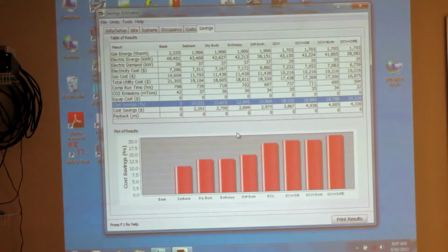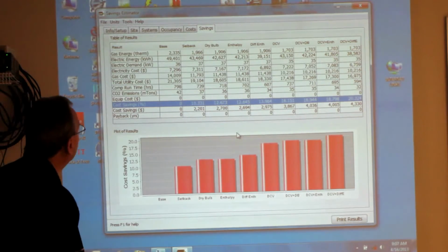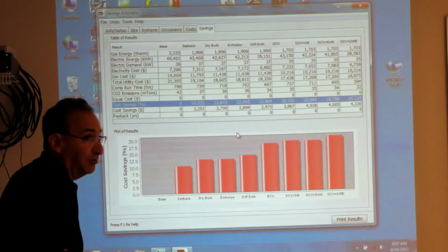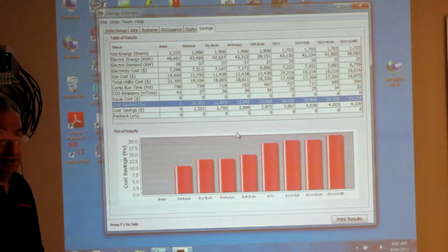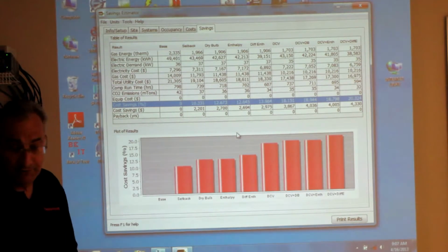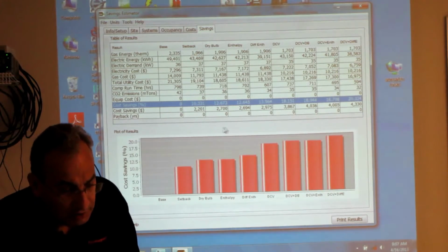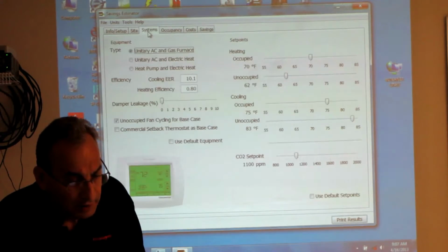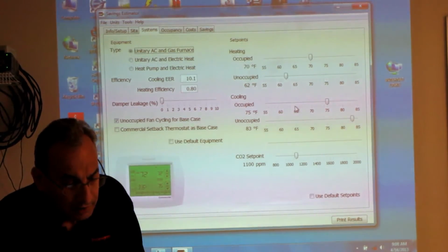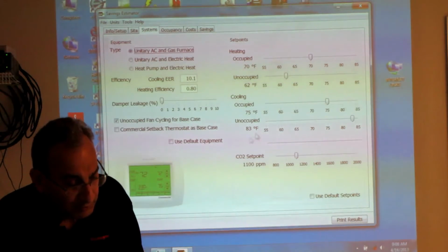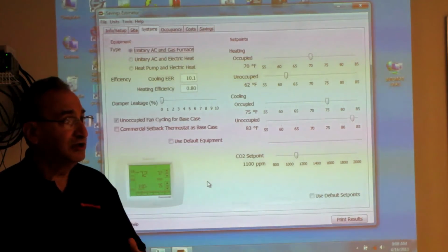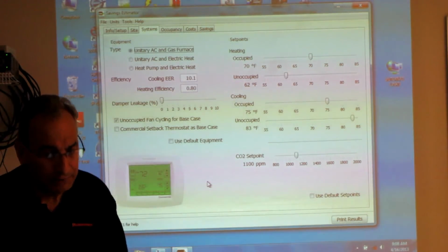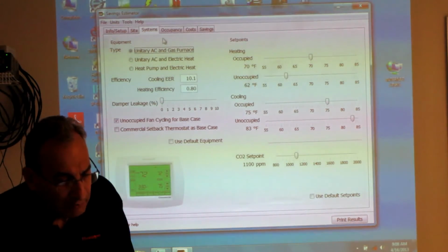Is that total? That first column on setback, how many degrees for how many hours is that defaulted to? I had to go back to the thing, but yeah, I had put it in there based on that occupancy. I'm just curious what the default was. You can blow that out of the water real easy if you don't have it set right, or if there is no setback, you know, if it's 24/7 operation. Typically, you have that in the factory and in the offices, you know, you have standard hours. And that would be under the occupancy.